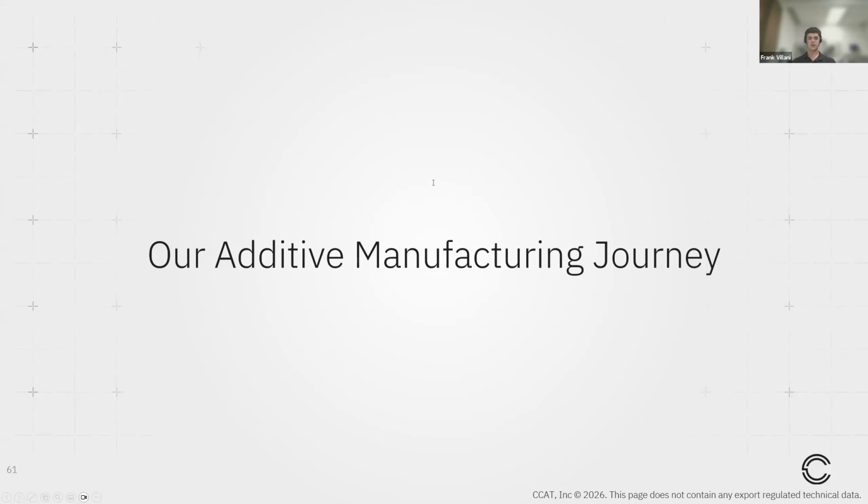I then was able to use one of our powder bed fusion methods, or SLS methods, to create some nylon components for the rocket, along with being able to use another FDM method, which allows me to lay continuous carbon fibers into, for this rocket, the fin can itself. So this rocket, even though it does fall into the model rocketry category, will be able to go about 2 miles high at the speed of sound. And I found it to be a fantastic demo. CCAT supported me on building it.